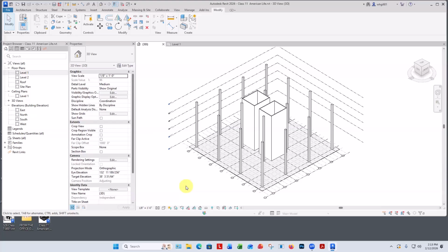What's going to be happening at the corners of this building in plan is there's a 24 by 24 column coming up at us. The walls, we're going to be treating them as 24 inches thick. They're mostly hollow, but that's how they're expressed architecturally. So we're just going to take our floor right from this corner right here down to the same opposite corner. We don't have to engage the floor into the wall at all. They're just like separate pieces.